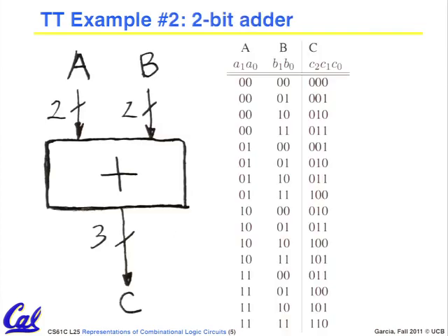Now, we've got the case that we're going to need an adder. At some point, we have to have circuitry to implement add, register, register, register. So we're going to need an adder. And let's start small. A 1-bit adder is nice, but let's think about a 2-bit adder. So here's a 2-bit adder, and here's the truth table. So you're saying, Dan, all I know how to do to build circuitry is to do it by a truth table means. Okay, here's a truth table.